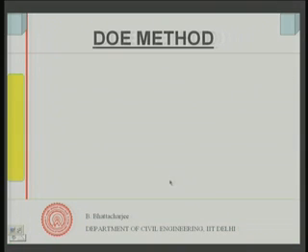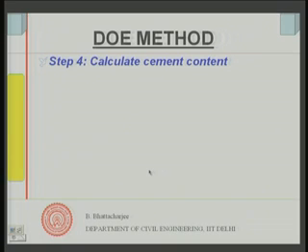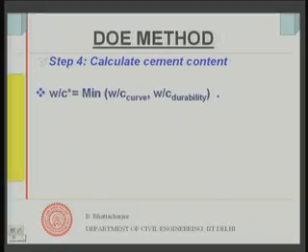Okay. Water content being known and water cement ratio being known, I can calculate the cement content. You see, water content is known, water cement ratio is known, so I can calculate the cement content, and it is calculated like this, like before, as in the case of the Indian standard method. Water cement ratio star, that means the one you will be using is the minimum of the water cement ratio you have determined from the curve and the water cement ratio that you have determined from durability requirement, from the same table.